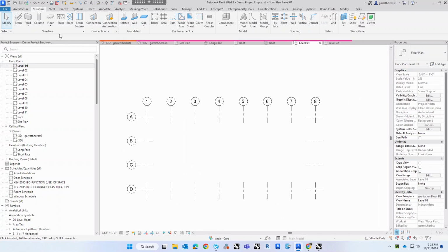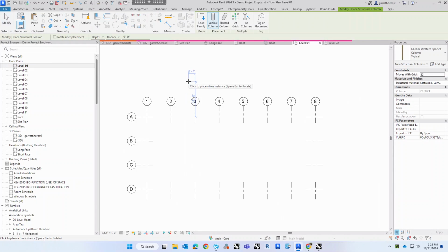Of course, in real life, your structural engineer is going to be doing that, but we still do have to place them, especially when we're starting a project. The structural engineer is not on board yet, and we obviously need to show structure. So when you select the main beam, what you want to be aware of is, for some reason, it selects depth over height when you first bring it in. So that is right here. And then you want to change the height of the column to be the level above. And then finally, you want to select at columns.